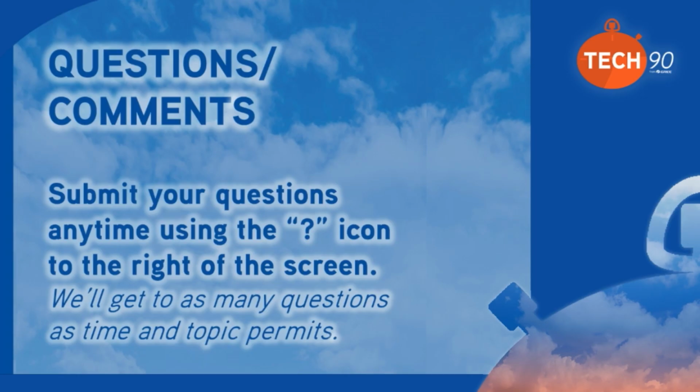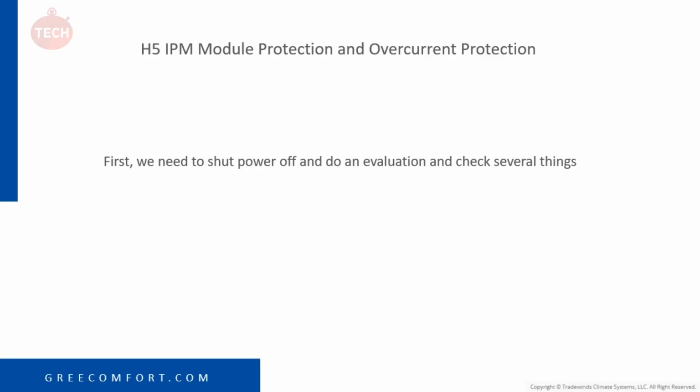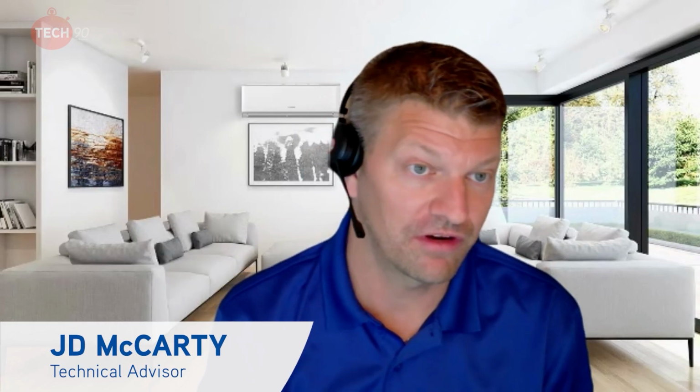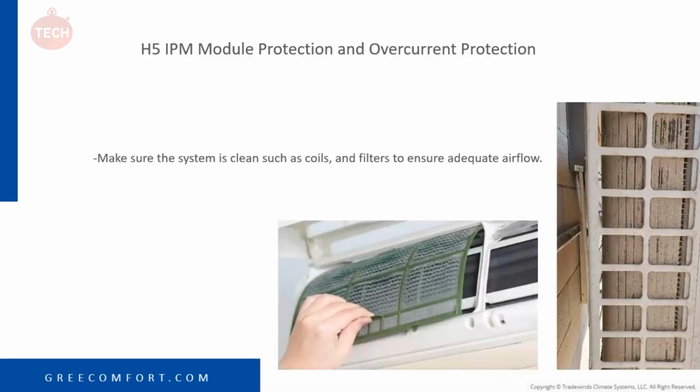All right. So now we're going to get into our last code. It's an H5 code, which is IPM module protection and overcurrent protection. First, we need to shut off power and do an evaluation and check out a few things. So this, again, is a hard reset code. So 10 minutes of off time. A couple checks we want to do.